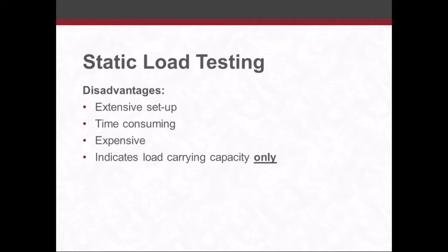Some of the disadvantages: there's extensive setup, which is time consuming, can become expensive, and it only indicates the load carrying capacity of the pile. Nowadays there is instrumentation that can be affixed to the pile to determine what the forces as well as deflections are throughout the length of a pile in a static load test.